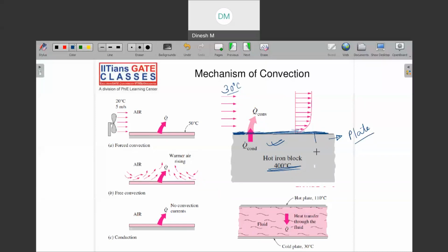and then you are conducting heat from this surface to the outer surface, and then your air comes in and picks away the heat. Then this air becomes hot, the cooler air comes again, you are conducting heat, and it picks up the heat. That means here we can say that conduction and convection both are happening simultaneously. Why? Because can you see this arrow? What happens here is that I am losing heat by conduction to the surface, and then from this surface convection is taking away the heat. That is why I can say that there is always conduction and convection happening simultaneously.